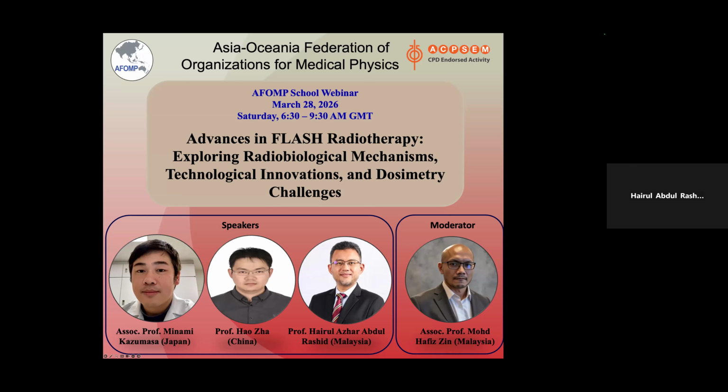So we could resolve up to 300 pulses per second. But nonetheless, as I mentioned earlier in the talk, at the higher PRF we could observe pulse pile up. So it's something that we have to work on, either work on a new material which has a faster decay response, or as we proposed and presented earlier, go with a post-measurement signal processing approach where we deconvolute and separate the signals to clean them out.